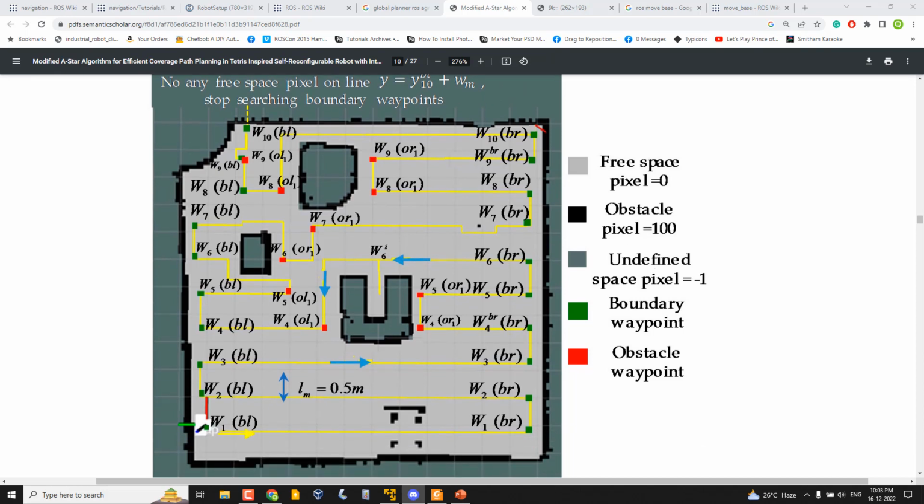Okay. So coming back to the point, the global planner may not be an intelligent planner which makes the plan when we give a goal position. It can be a fixed plan as well. What the global planner does is that it gives a global plan. That's it. If you want to create a fixed plan, that is also possible. For example, in this case, we can do it in two ways. If you decide that there is a fixed map and you just want to drive the robot through this fixed path, that is also possible.